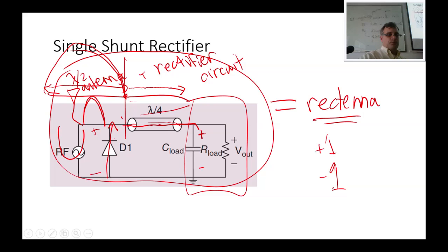Which means there's no place for the signal to go. This is shorted out. So by the time you get to the end, let's say half of the wave has made it onto the transmission line. The end strikes here, and all of a sudden you get the opposite voltage reflecting back. So this pulse reflects polarity.